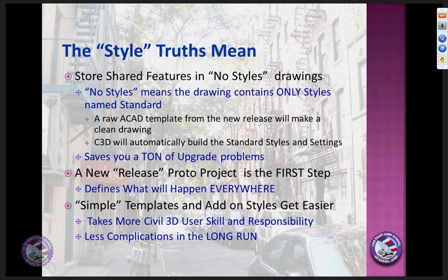The problem is our madness: software might not understand, and all of a sudden things are all chewed up, and things don't publish properly, etc. So storing your existing surface and your final proposed surface in these kinds of drawings gets you over the problem of, well, it didn't upgrade and it's your fault. It really eliminates that probability, and actually you will find if you practice this religiously, your whole project will be cleaner.